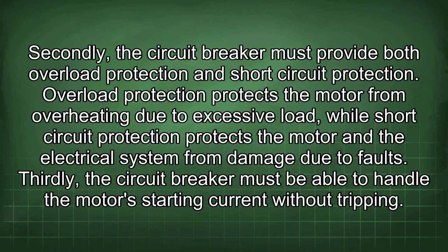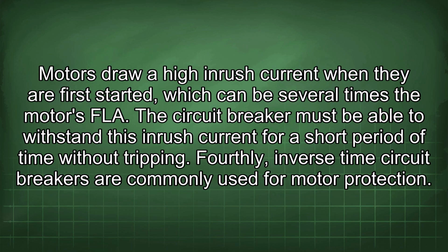Thirdly, the circuit breaker must be able to handle the motor's starting current without tripping. Motors draw a high inrush current when they are first started, which can be several times the motor's FLA. The circuit breaker must be able to withstand this inrush current for a short period of time without tripping.